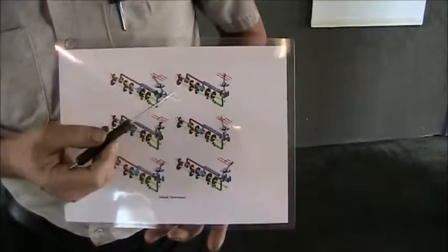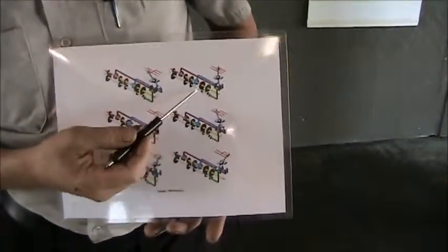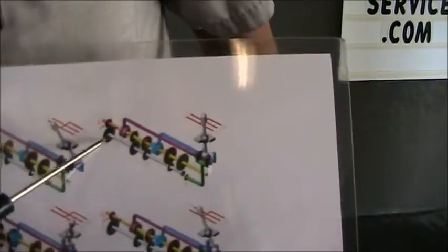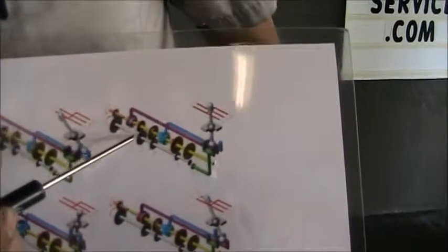Remove your gear selector, and all of these gears are constantly in contact with each other. All you're doing when you select the gear is connecting that gear to the output shaft. So all these gears are free spinning. They're not connected to this shaft until you select it. So you select this gear to be connected to the shaft, and then it uses this gear ratio right here to complete the output gear ratio of the transmission.